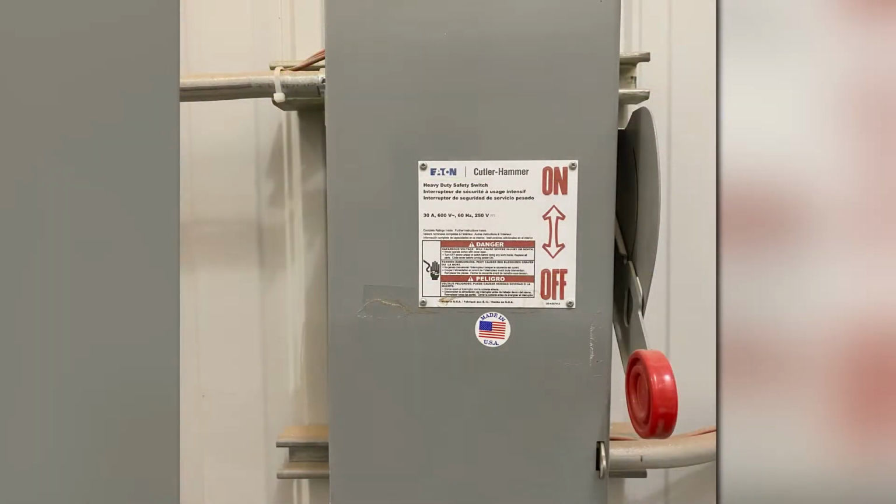One of the simplest solutions to reduce both electric usage and demand is to turn off motors when they are not in use. According to the DOE tip sheet on this topic, reducing the motor runtime by just 10% usually saves more energy than replacing the standard efficiency motor with a premium efficiency motor.